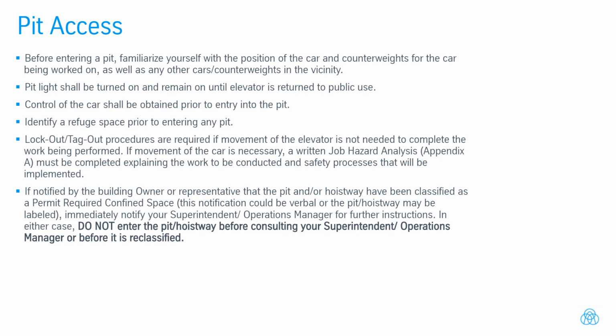Before entering a pit, familiarize yourself with the position of the car and counterweights for the car being worked on, as well as any other cars or counterweights in the vicinity. The pit light shall be turned on and remain on until the elevator is returned to public use. Control of the car shall be obtained prior to entry into the pit. Identify a refuge space prior to entering any pit.